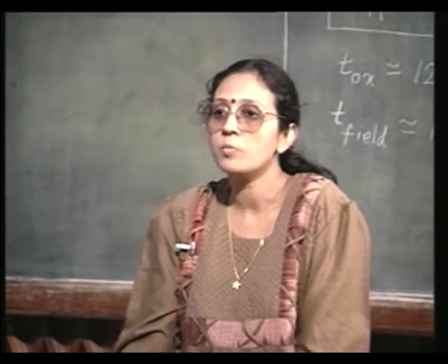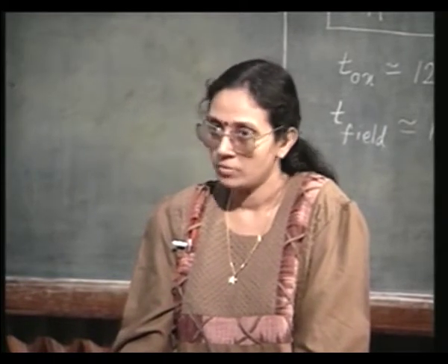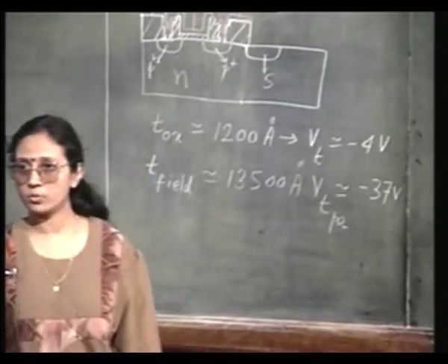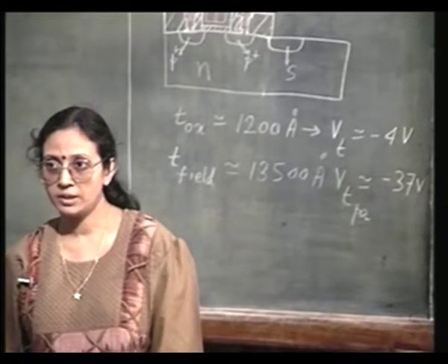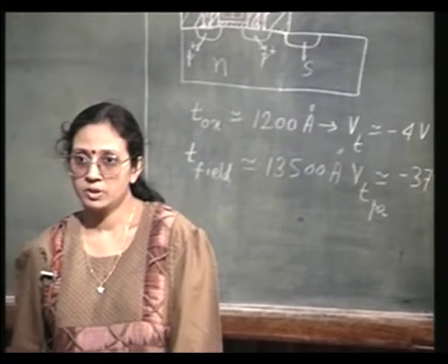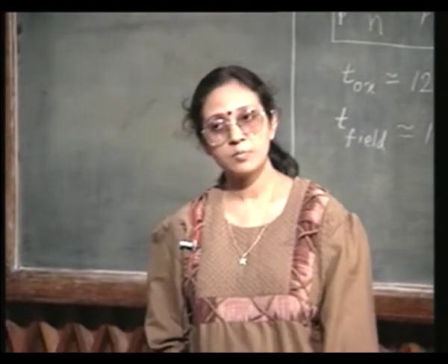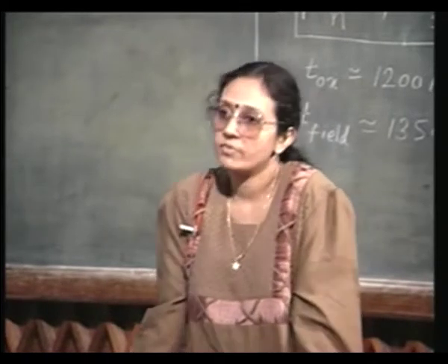You see, in a PMOS we have a negative gate voltage. So, you have a negative threshold voltage which works perfectly. When you apply the gate voltage, only then the MOS device is getting turned on, fine, no problem. By the same token, in an NMOS I apply a positive gate voltage.